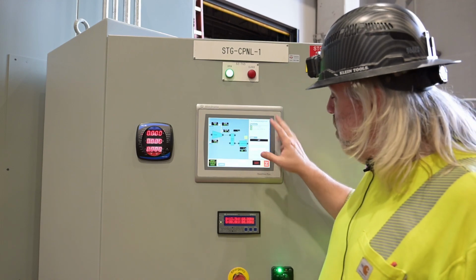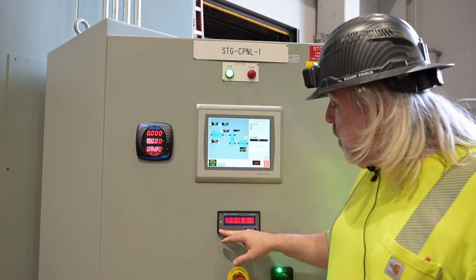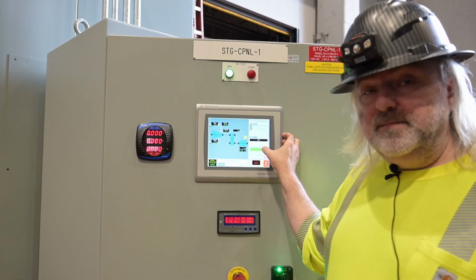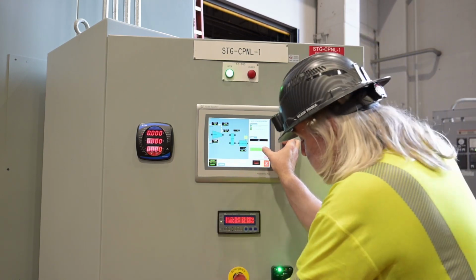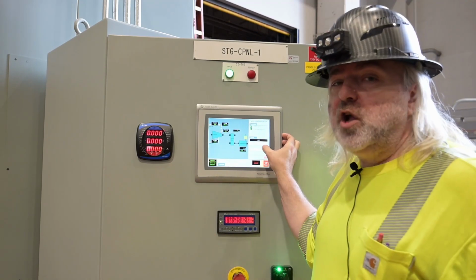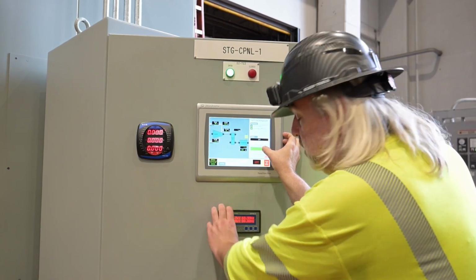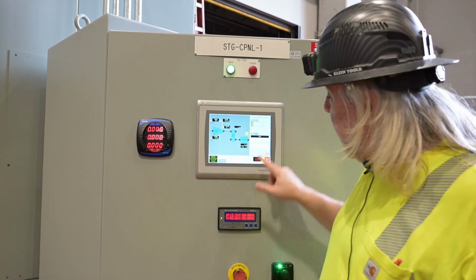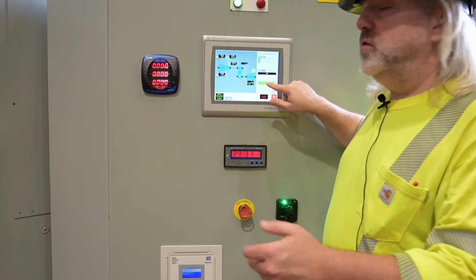So in manual, you've adjusted your voltage and frequency properly. Our sync scope is going slowly in the fast direction, and then you can hold this button. Once you're holding this button and this device agree, the breaker will close. This button does not close the breaker. This button just approves the synchronizer and the sync check to close the breaker. So again, you do not have to wait to press the button. You can hold the button. Once you're in phase, it'll close.